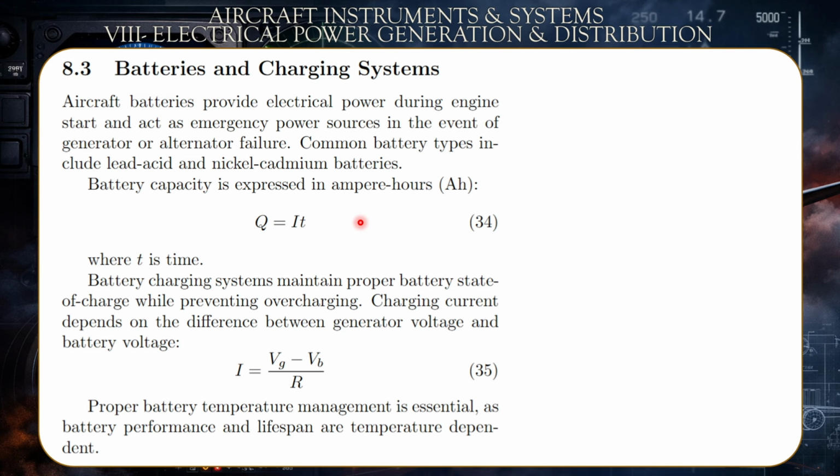So let's say it's 200 ampere hours. However, it can be filled to 95%, not more. So you multiply it by 0.95, and it can be discharged 90% also, so you multiply again by 0.9. This is all that you can use, and you divide it by 2 amperes. It gives you how many hours it would last before it disconnects.